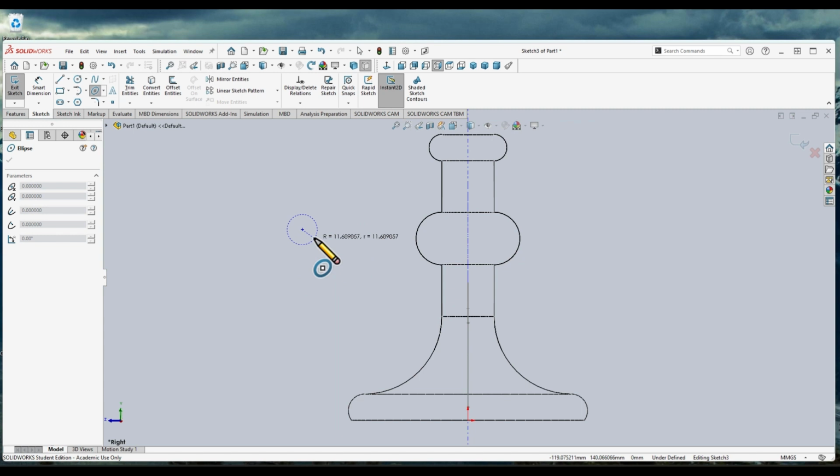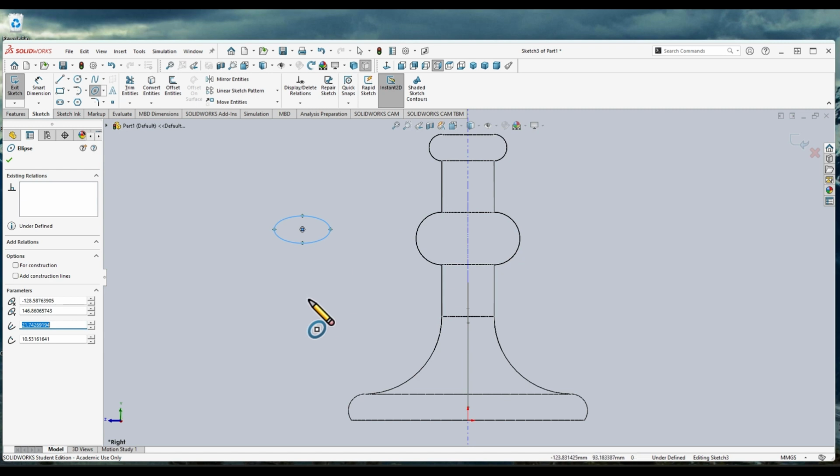While I draw it, the first click starts drawing this dotted circle. I want to make sure that I don't draw this at some weird angle, so I want to have it coming off to the right or the left, depending on your preference. It doesn't really matter. It's at some arbitrary size, because I'm just trying to make a rough sketch here. When I left click, it locks that into place. Now I can move up and down to give my ellipse its ellipse look. Once I make it look ellipse-like, I left click again, and that locks it into place.